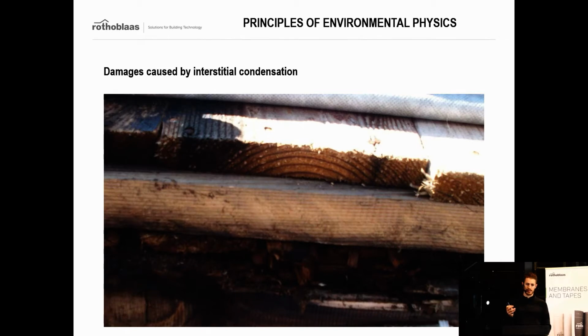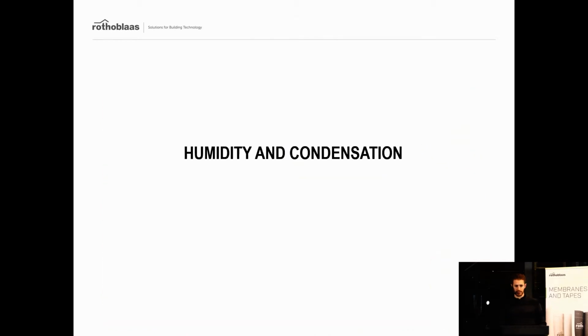And as you can see, when they opened up the floor buildup, they saw that all the timber structure inside was completely rotten. So this is a picture to keep in mind when you're designing a timber structure, because the design with the right membranes is very important to make sure the durability of your building works in the right way.